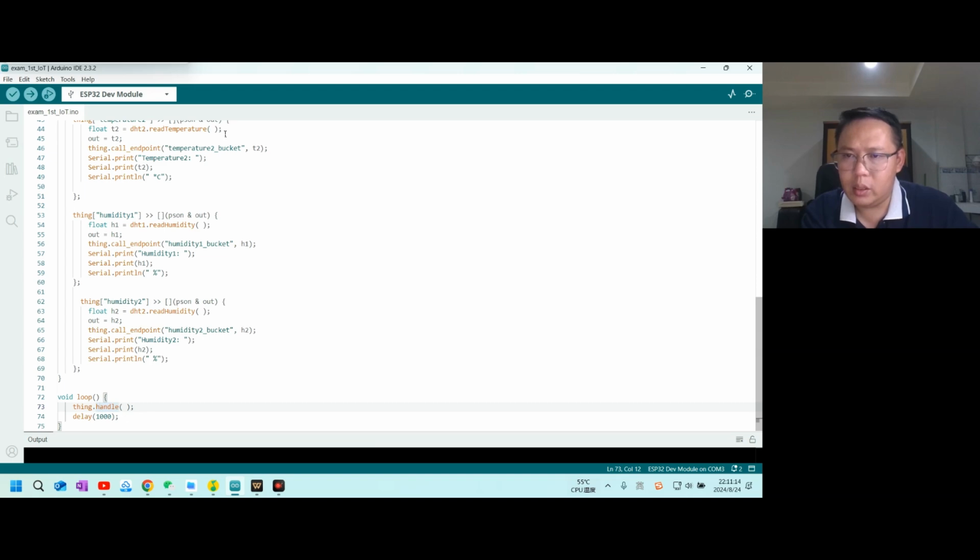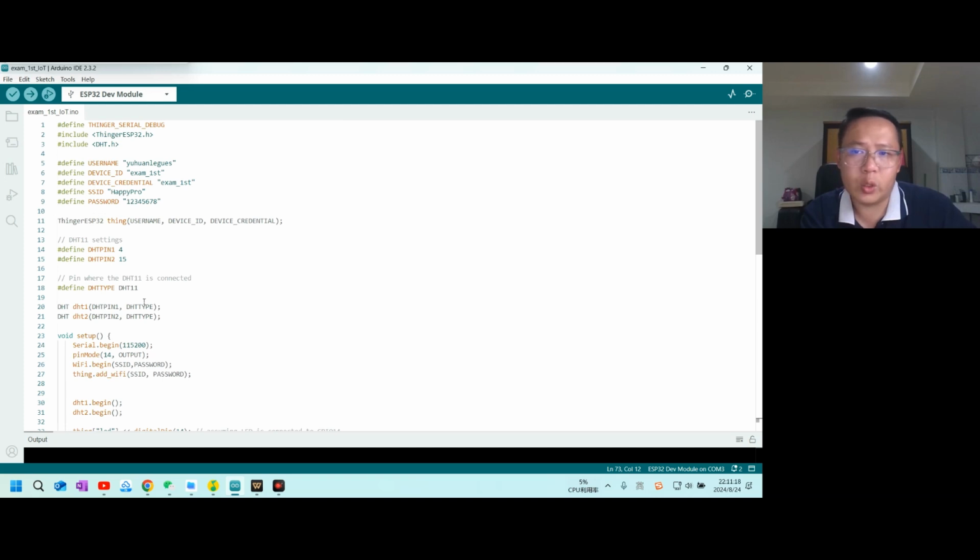Okay, this is the program introduction. Next, we can choose the board ESP32 and the port is COM3. Okay, it's correct. We can upload that. Wait a moment.